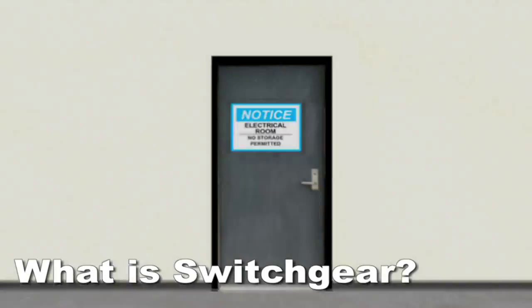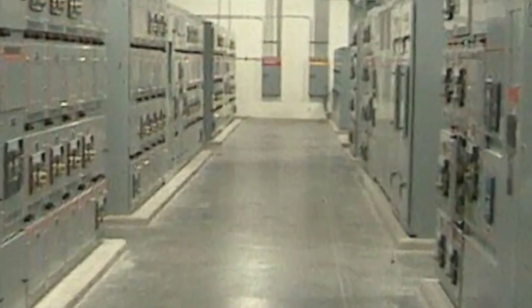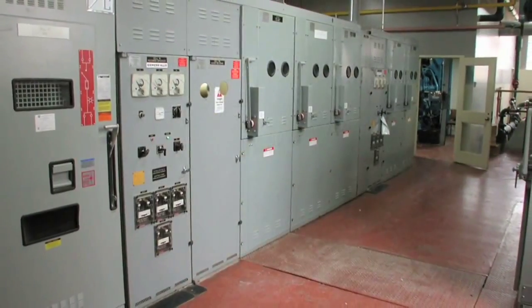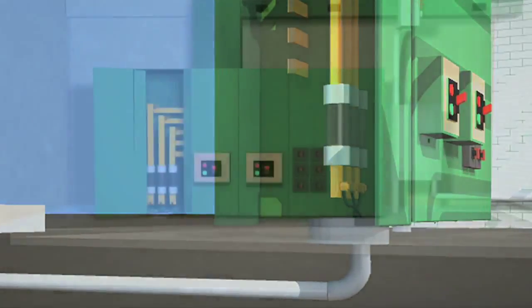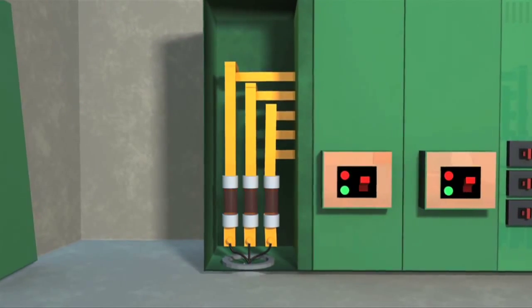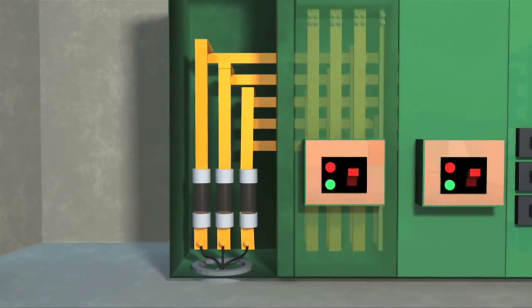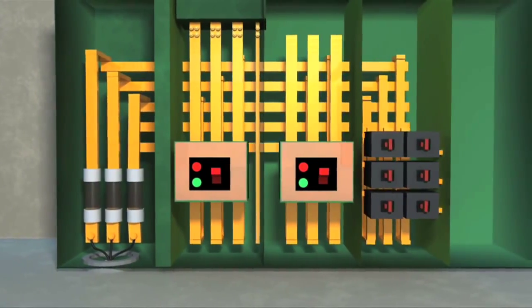What is switchgear? It's the beginning of the electrical distribution system inside the facility, located in an electrical room. It is made up of several sections containing switches and/or breakers. The first section receives the incoming power from the oil transformer. The wires are connected to a main breaker, or in this example, they are attached to fuses. The fuses are connected to bus bar. Bus bar is either made up of copper or aluminum. The voltage travels through the bus bar to each section of connected switchgear, energizing each section.